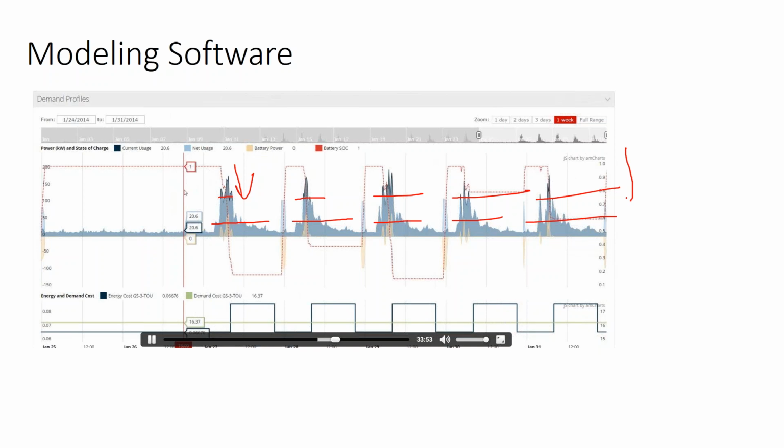So there is kind of an optimal point on cost and battery runtime to say, when you're load leveling these short, spiky peaks, that's going to be a lot more cost effective than trying to demand manage all the way down to your building's base demand.